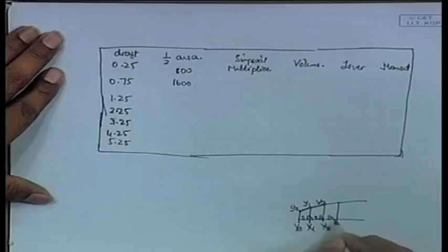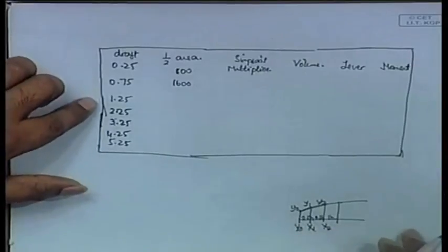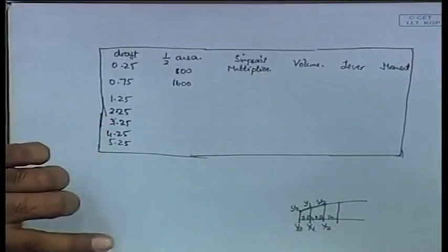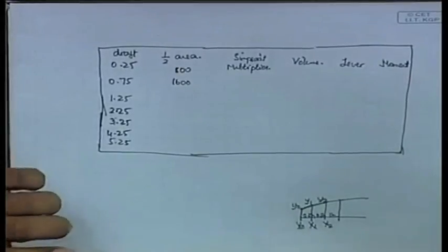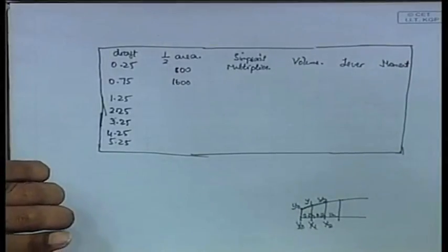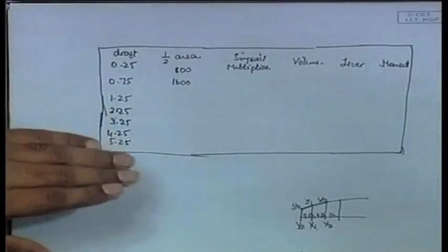Next one is 1h. That difference comes because of the different type of stations. With that, you derive that. Rederive the equation for the area. I will ask you to do that for some time, and when you do, you can get the real value of the Simpson's multiplier for that particular case.